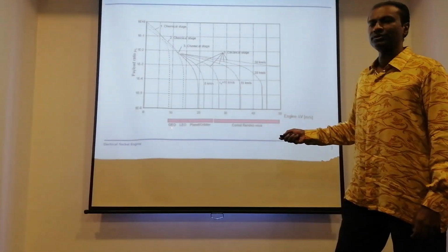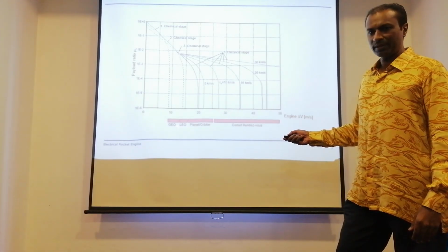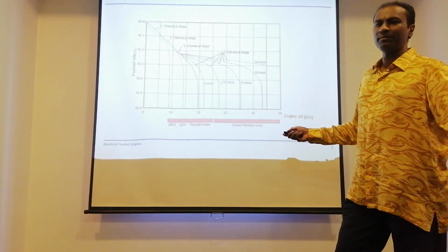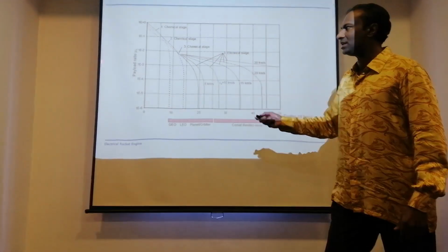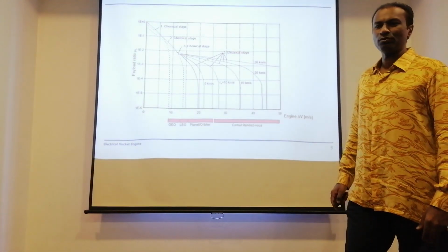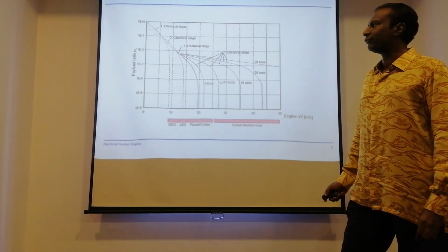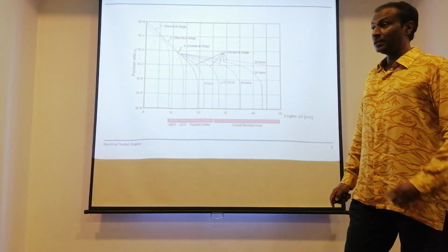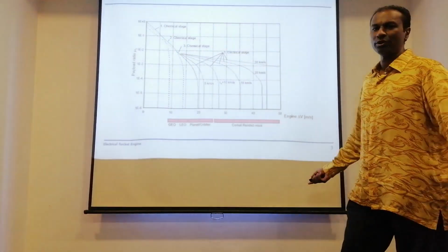GEO, geostationary orbit, planet Earth, LEO, low Earth orbit, planet Earth, orbiters. If you talk about a moon mission, you can look at orbiters. All these are within our Earth vicinity. So for this kind of mission, I would go for chemical engines rather than electrical engines. But if I want to go far, looks like I have no choice.